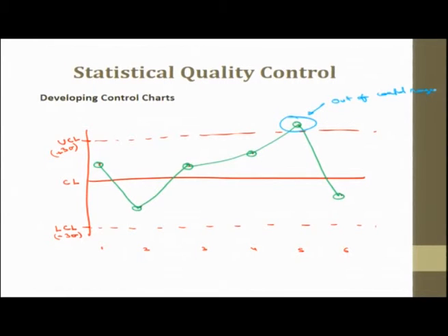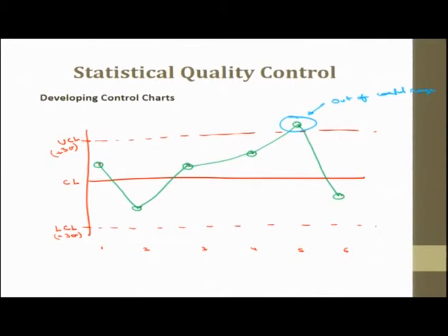This kind of error, sometimes it is random, like the plot goes 1, 2, 3, 4, 5, 6, 7, 8, a spike comes at 9, then it comes down. This can be random, with no assignable causes. But in this plot which I have just made, I have just picked some random data, you can see there is an increasing trend. It may be inferred, I am just saying maybe, it is not for sure, but we have to see the actual experiments and whether that is true or not, that an error started from point number 3, kept on increasing, went out of control, then came down. It might be that the instrument you are measuring with has deteriorated, or the observer is having some parallax error. Any kind of error could be there, but this is an increasing trend.